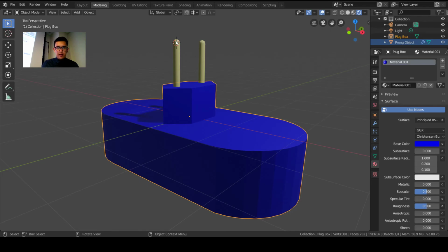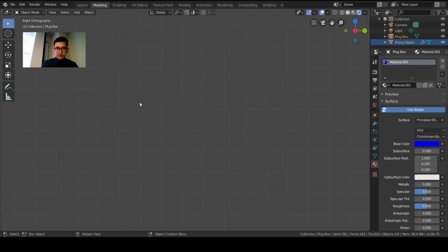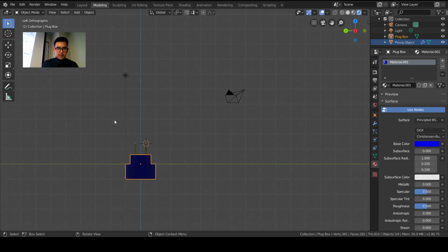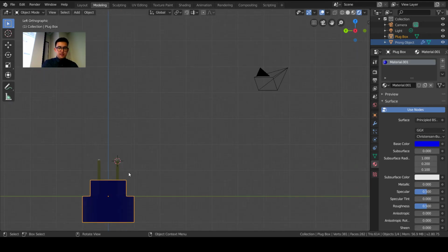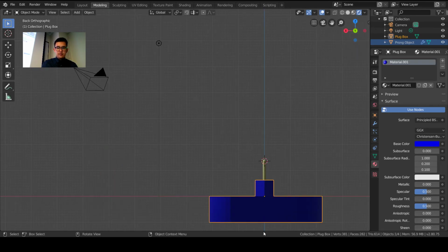So to do that, I want to align my 3D cursor with somewhere on this plane. So let me press Home. Okay, so I pressed Home, and I'm in this projected view. But let me just go to the Y face by clicking Y on the gizmo here.